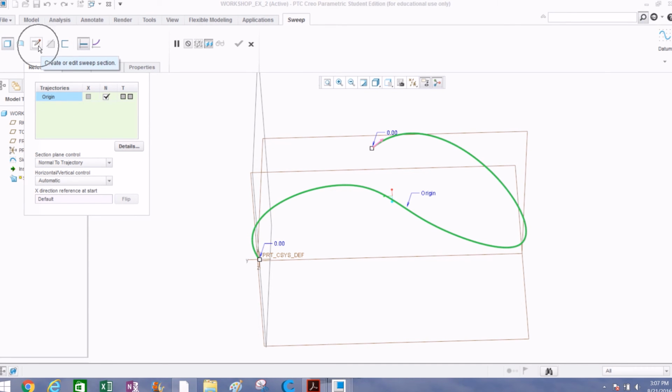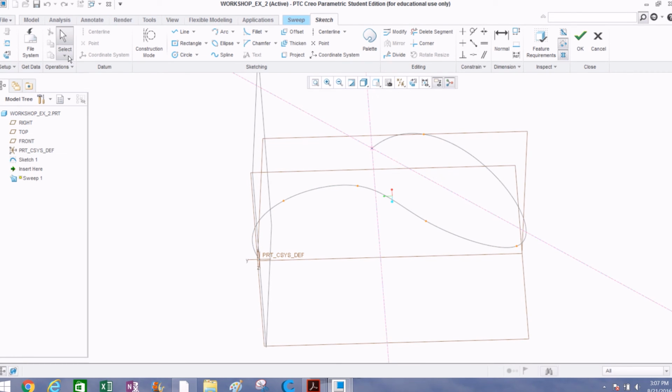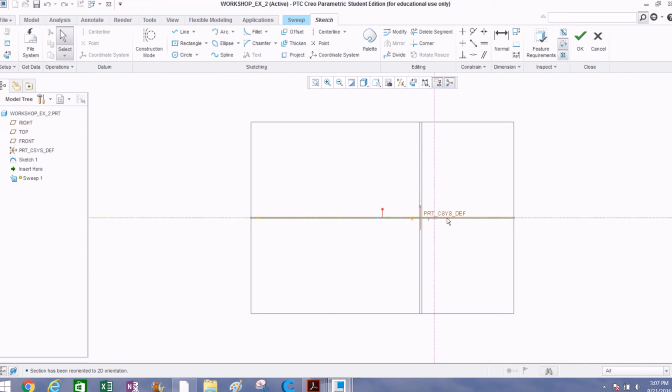And we're going to go up to the left to the sketch tool. Once we click that, it'll allow us to sketch. It should be selecting one of these edges here. You see it's this one here. So we'll go normal to sketch and draw something. It could be anything. What I did notice with this is you do need to have the feature as part of it. Before, if you hit corner and sketched on the origin of the plane, clicked it once and dragged off to the side, it wouldn't actually work. So you're going to have to use the center rectangle, grab that center point, drag up, create something, and make this tall looking rectangle, center click.